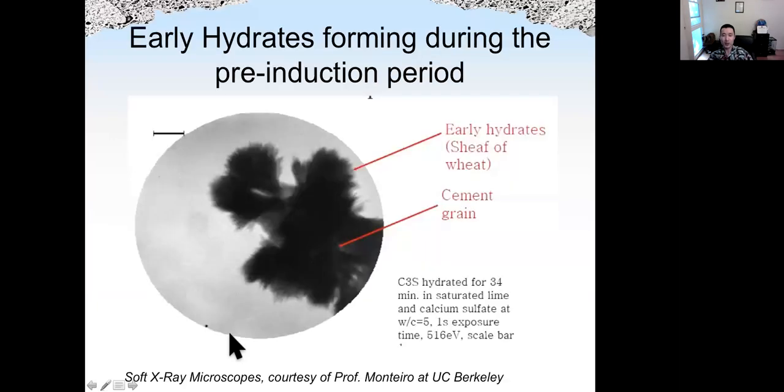Alright, so when you mix water with cement particles, you can think of the cement particles as suspended in the water. The cement particles are not connecting to each other, because we have a lot of water in it. When we have hydration product, this hydration product will precipitate on the surface of the cement grains. So we have more and more solid. At a certain stage, the nearby particles will connect and stick together. So we have hardened concrete. We have initial and final set time.